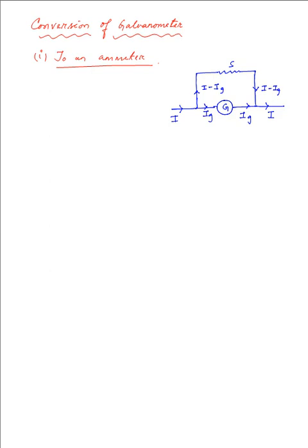However, in practice, we have to measure large currents, and in that case, a suitably low resistance, that is the shunt resistance, which is S that I have indicated over there, is connected in parallel to the galvanometer, and this arrangement forms the ammeter. Now, what is the value of that shunt resistance which needs to be known in order to get the galvanometer to work on a given range or on a given scale?